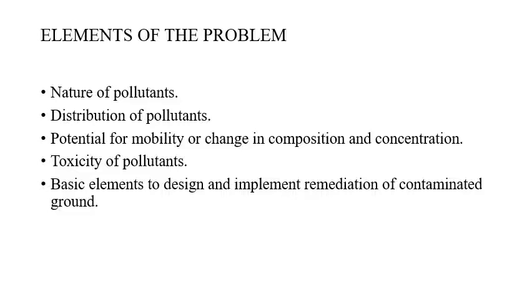So basically, in order to arrive at a proper solution, or to remediate a contaminated land, you will have to understand the nature of the pollutants or contaminants. That will be known to you only if you conduct a proper subsoil profile investigation through some tests, just like how you conduct a normal subsoil profile test before you start any sort of project.